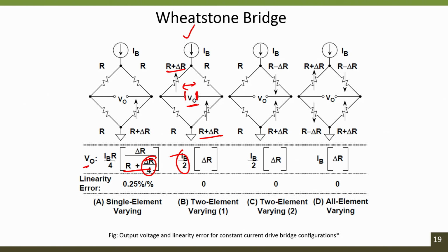So, in such cases we cannot use either an inverting amplifier configuration or a non-inverting amplifier configuration, because the inverting or non-inverting amplifier configurations can only amplify or attenuate a single input voltage with reference to the ground, whereas in this case it is differential.